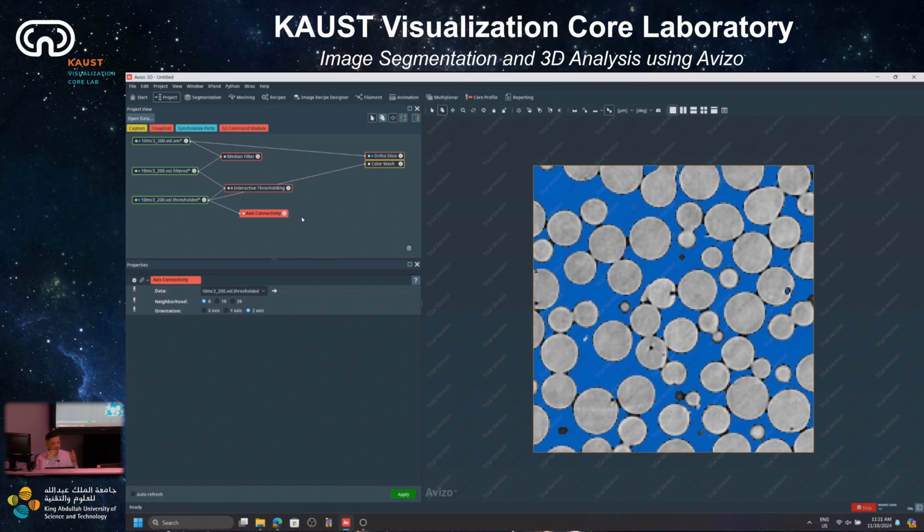If you have a voxel as a cube, 6 faces, that's the minimum neighborhood. But if you consider the maximum, that means even on the edge and the apices, if voxels have edge contact, they consider this also a contacting point. It depends on you if you want to have the minimum, but it's recommended for simulation to use the maximum contact on face.